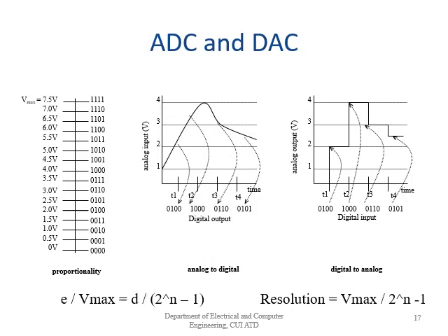So in this slide we are going to talk about analog to digital converters and digital to analog converters. So first look at this table. In this table we are using 4 bits because we want to represent 0 to 7.5 volts. So you can see here that we have a resolution of 0.5 volts. Why do we have a resolution of 0.5 volts?